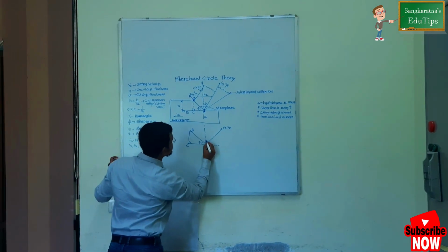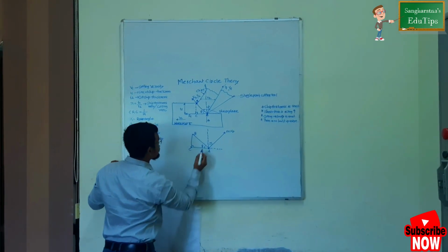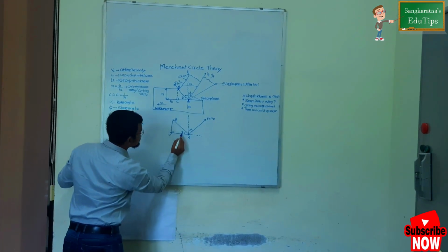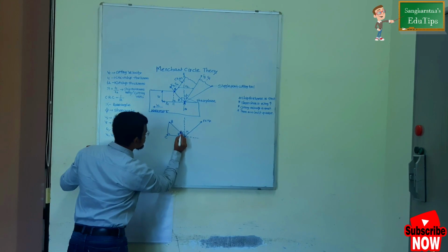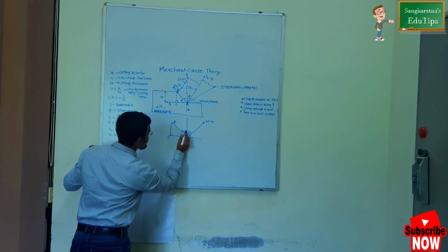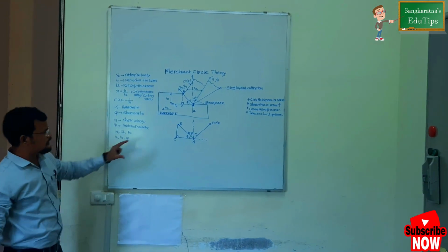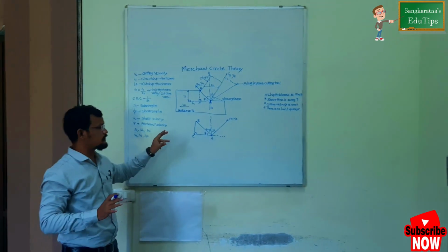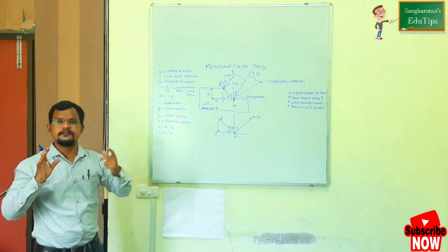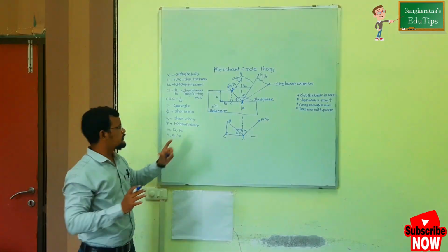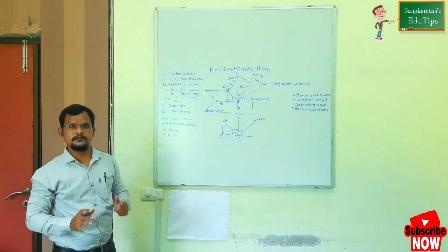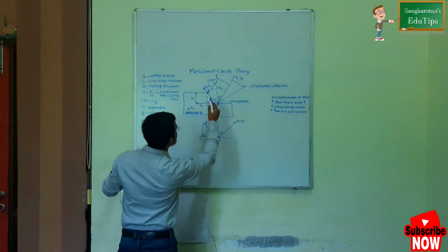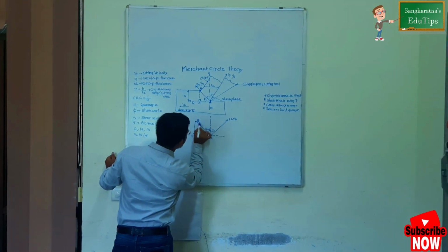This angle is alpha, the rake angle. From this it makes a 90 degree angle with this. So this angle is phi, and this angle is 90 minus phi. It is very important to understand which angles are present in the diagram. Once we are able to determine the angles, we can easily calculate the various forces generated during the turning process, right?